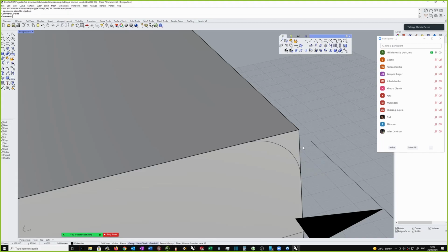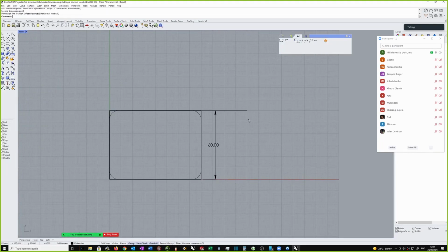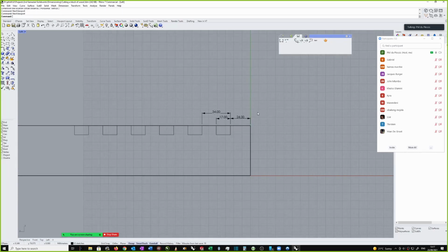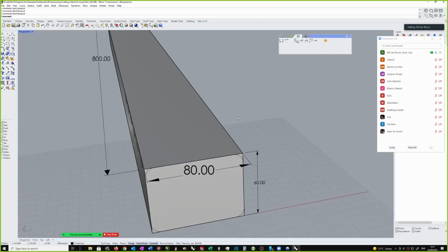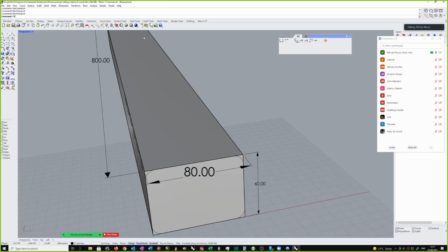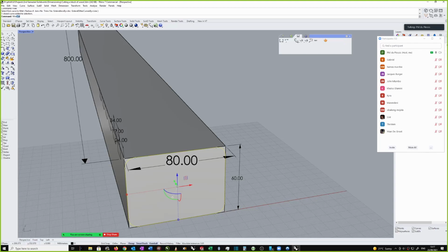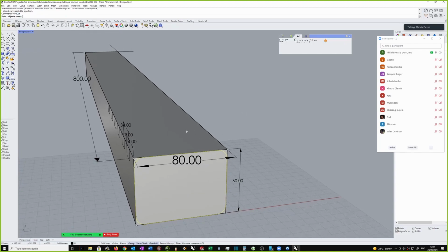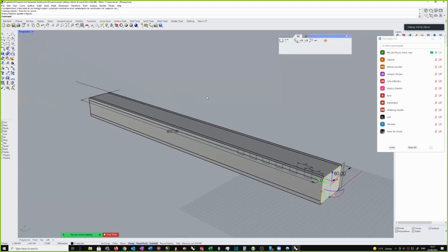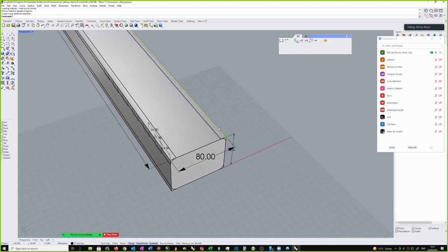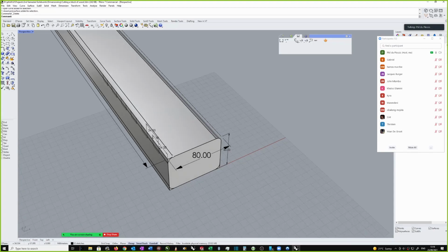But in the workshop with the milling machine, what they would do is add an 8 millimeter radius, or a diameter 16 bullnose cutter, or you'd put a router on with a curve in it, and you'd route this end off. Whatever it is, we're going to do all of them at once, and we'll go all the way through. Okay, so you would have chopped off your 4 fillets like this.